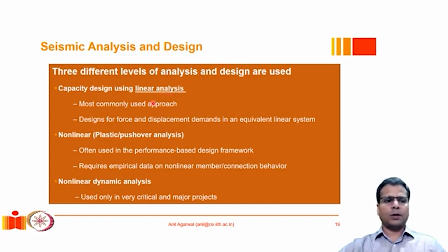This is the most commonly used approach, and the idea here is that even though we expect the system to behave non-linearly, and we expect the structural system to form hinges, we design the individual components only up to the elastic limit, and then we use some kind of scaling factors to calculate the actual performance of the structure.